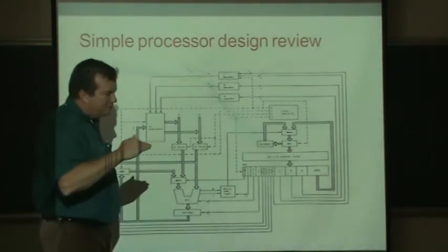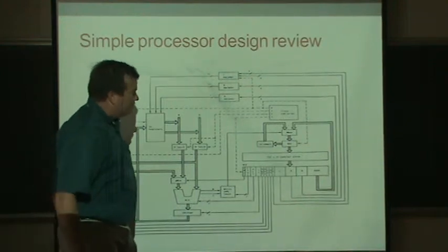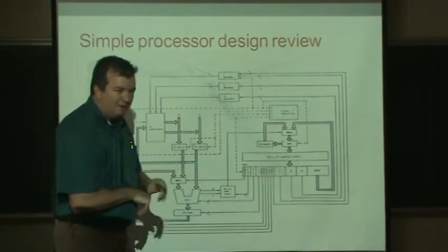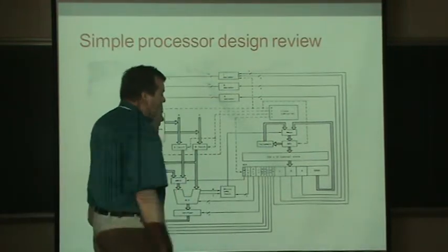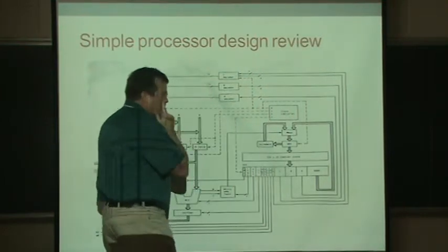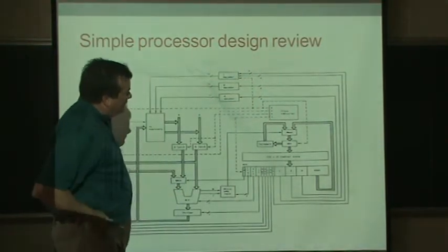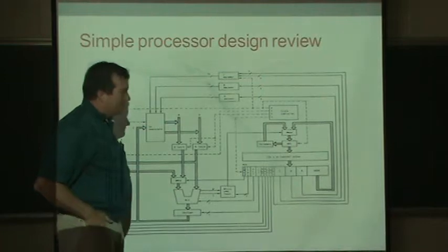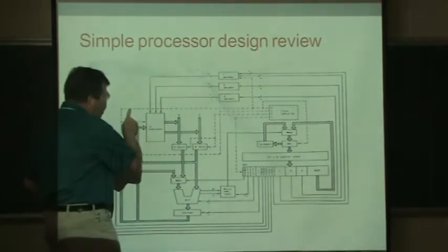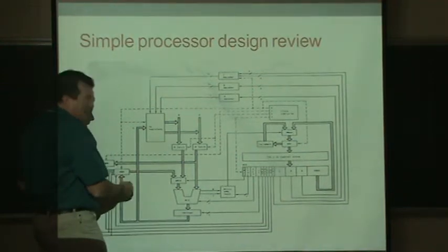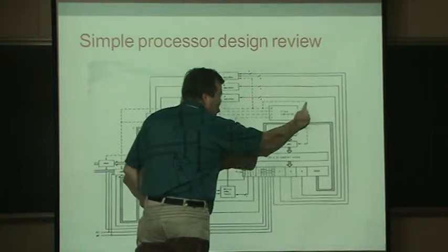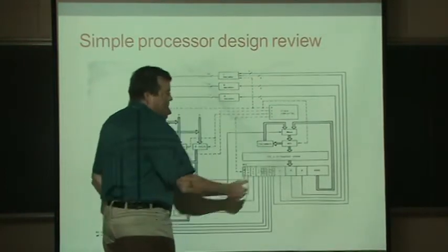So we have these different steps. On this processor, our clock, here it says clock subcycles. I don't know if you can see that. Clock subcycles, and it has 4 steps. Step 1, step 2, step 3, step 4. And since this was a really, really simple design, if you notice step 4, the final step, which is where we are actually writing data back to memory, during the final step, we are also simultaneously picking up the next instruction.